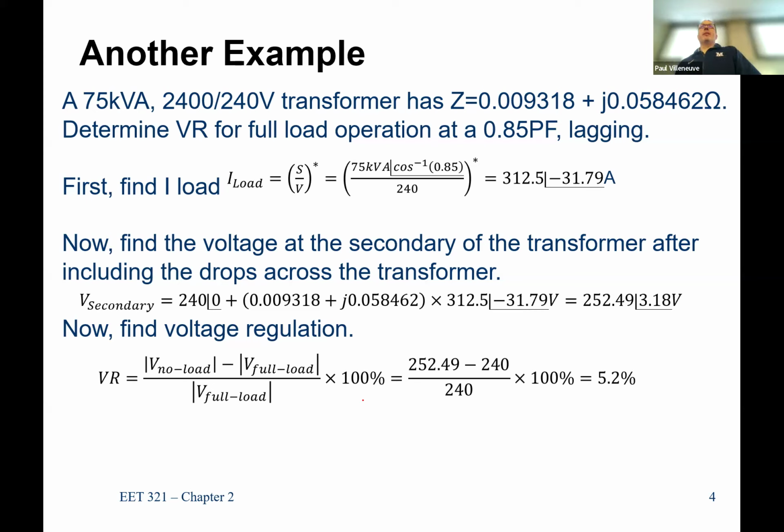We talked a little bit about it, but fire, right? You have oil-filled transformers. If those leak oil, you can get a fire and cause the building to burn down. But remember, old Barrows was built in the 60s, so you didn't have the same concerns as you do today. That's why the new Barrows transformer is located between Neville and the new section of Barrows, right next to the generator. It's an oil-filled pad mount, and they step the voltage down to 208 into New Barrows. That transformer is located completely outside. That's a lot more expensive, but nobody will insure the building otherwise.